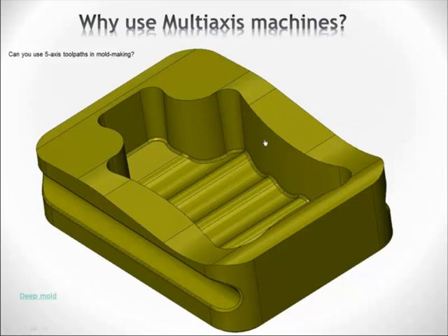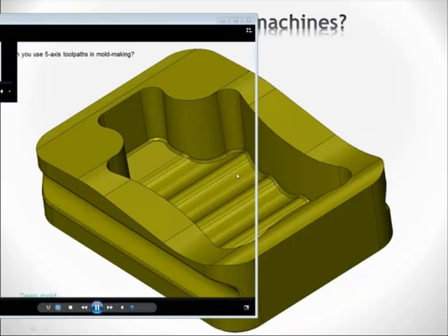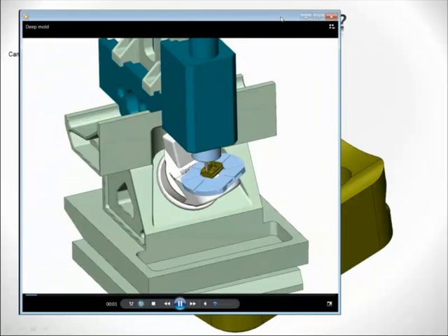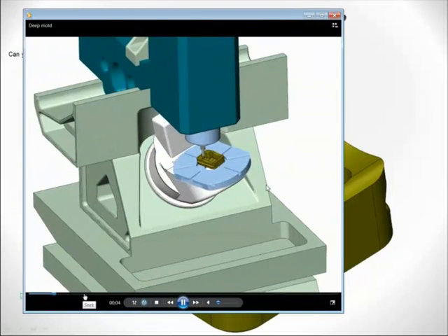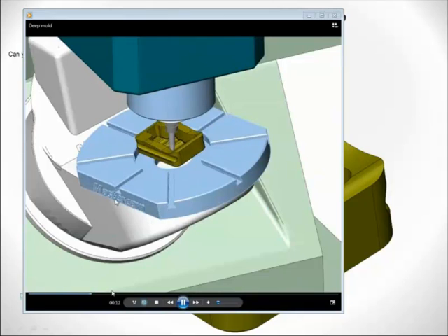This fillet is next to this wall that usually has a 1 or 2 degree draft angle. It's a deep pocket, so you would have to get in again with a skinny ball nose cutter to cut this. If you have a 5-axis machine and you can program a 5-axis machine in Mastercam, then you could use a tapered ball nose cutter and tilt it away from that wall. And this is the example that shows what that would look like.